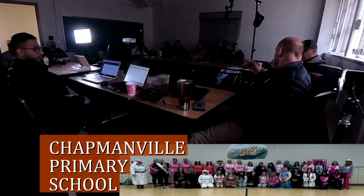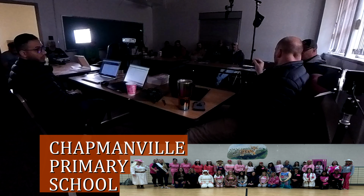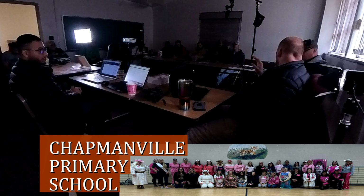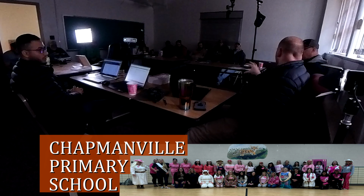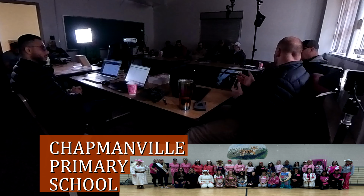So here's the thing too, I'm doing a federal building out in Parkersburg right now, and for every alarm that's generated on the active alarm, when they acknowledge it and it returns to normal, every time they go in and accept an alarm, they've got a comment screen that comes up, and they've actually got to write what they did to fix that, or why that alarm generated, and what the solution was to fix it. So that's another option too. On every alarm, you can have somebody go in there and write, hey, this fan is bad due to a squirrel cage issue, you know, whatever. So that's an option too.